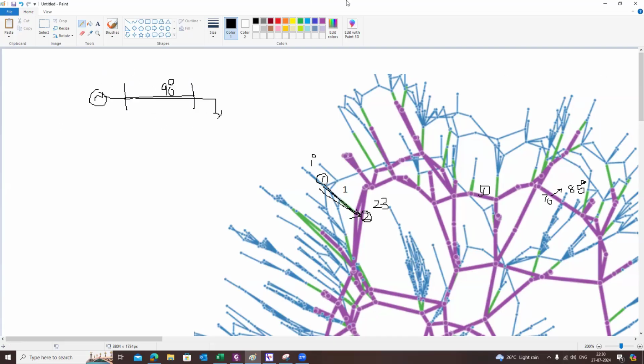Our system is an interconnected system. So the 90 degrees we are talking about in the interconnected system is from the lowest angle of any bus to the highest angle of any bus. Whereas the angular difference between two adjacent substations connected by transmission lines is allowed up to a maximum of 23 degrees. So this is precisely what I wanted to explain. I hope this makes sense.